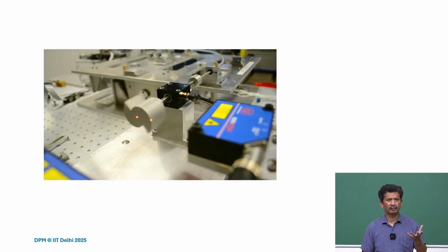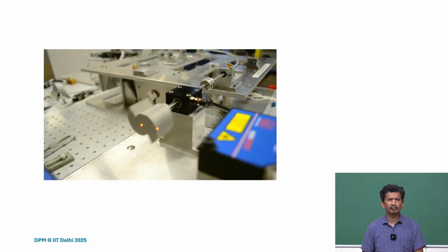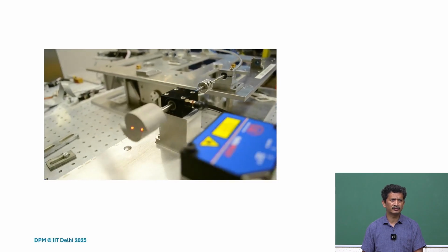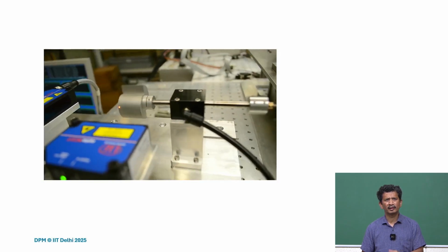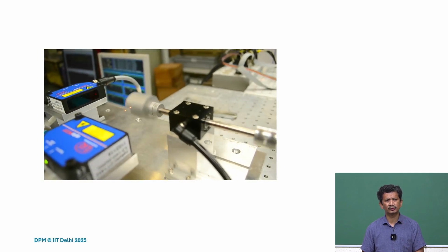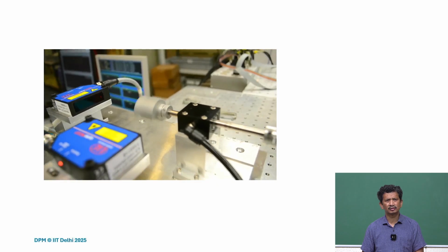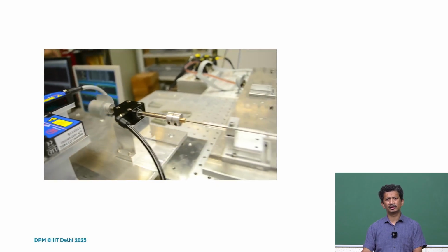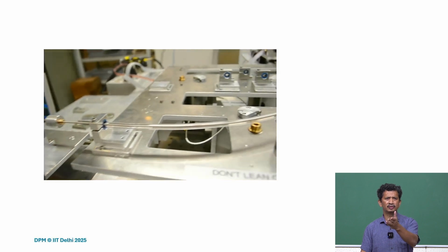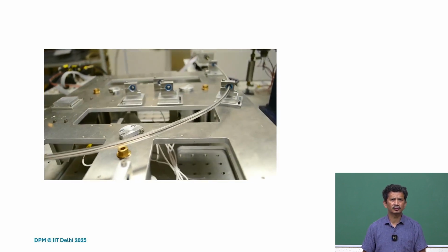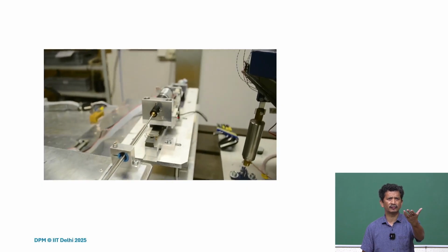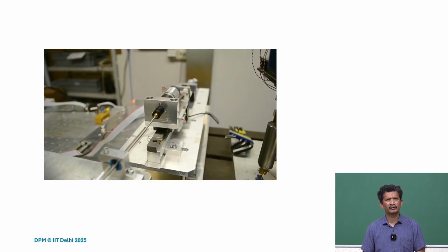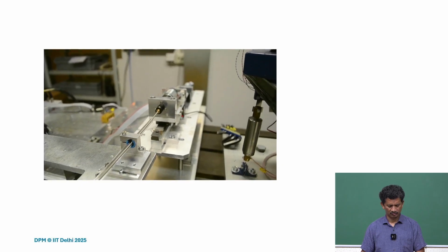So right from measuring the tip motion using the laser displacement sensors, using a cam, and then an air bearing to support the rod so that we should be able to measure the force only in the tube, not because of the friction from the support, and whatever the actuation force is there, it can be measured. So that we can see.